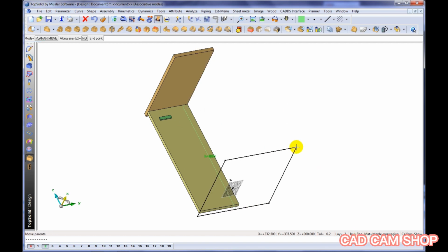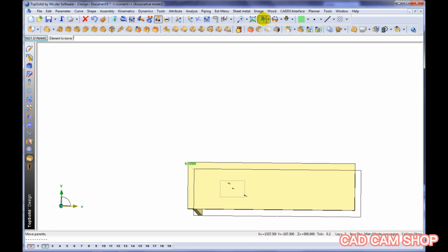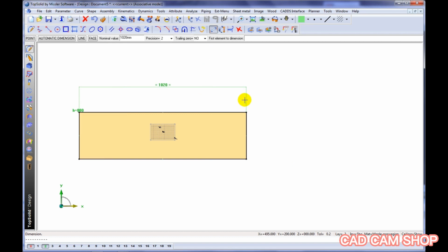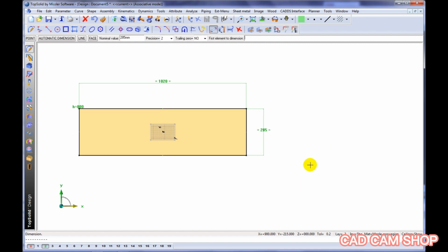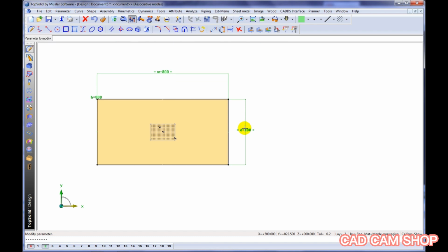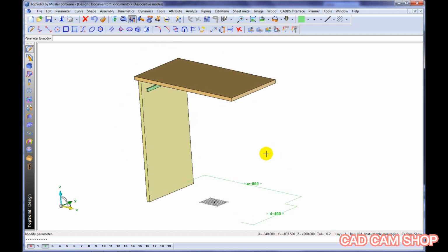Now if you look, if we drag this sketch around that created that initial volume, you can see that our parametric design is doing exactly what we had intended. So now we're going to make it a little bit more parametric, and we're going to add some driving dimensions to that initial sketch. We'll make them symmetric about our 0. Add this one, make it symmetric about our 0 as well. And then we'll modify them, set them to some kind of fixed value, as well as name them. So you can see, nothing very difficult here. And like that, those dimensions will be used later to drive the overall width and depth of our design.